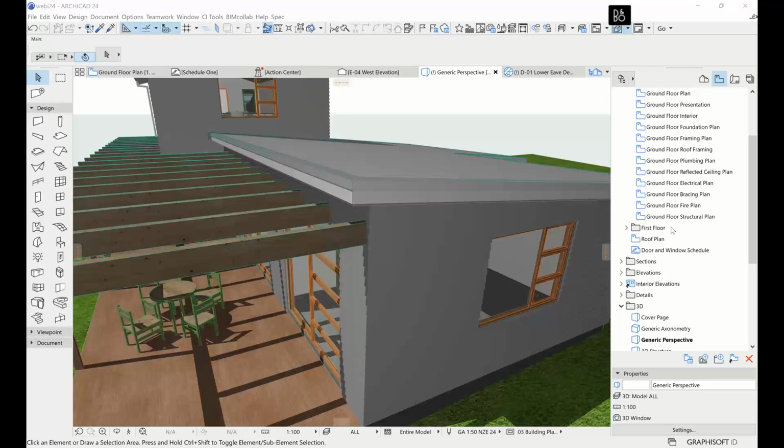As you might know, I can't remember when the shell tool came in, but back before then, we used to draw roofs using the roof tool and just a really multifaceted roof. The roof coverings will still work on those types of roofs. So if you draw a roof that is curved by just a bunch of flat facets in a curved shape, the roof covering will apply fine to those. But if you are using a shell, it can't deal with that at all at the moment.